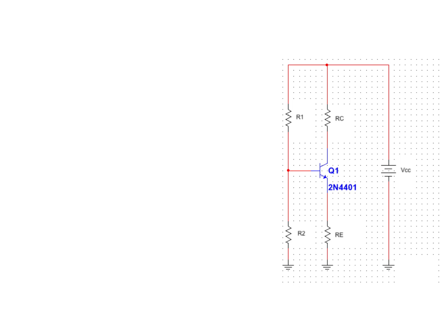So we want to find the voltage across R2, which is really the base voltage. If you're looking at any material I provided for you on the base current model, you'll see this called the Thevenin voltage.